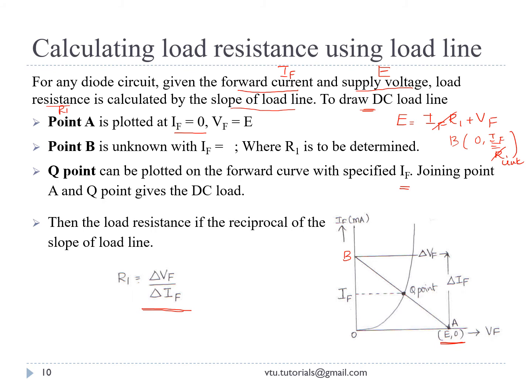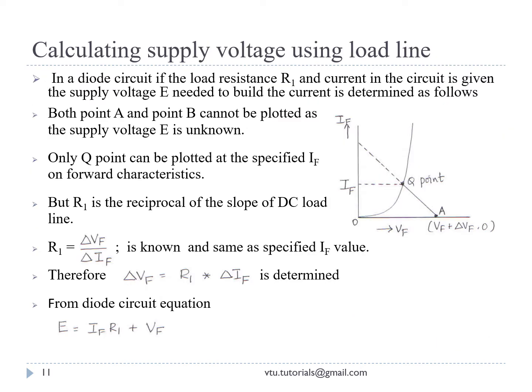Next, calculating the supply voltage using the load line. Determination of the supply voltage: if the supply voltage is not given, by knowing the load resistance R1 and the current in the circuit, we can determine the supply voltage. So once again the same equation, E is equal to IF R1 plus VF. VF will always be known.